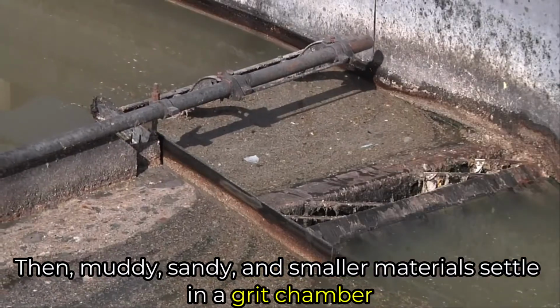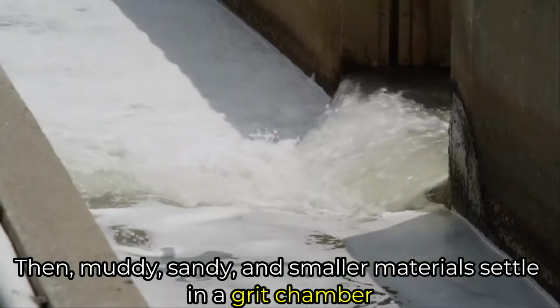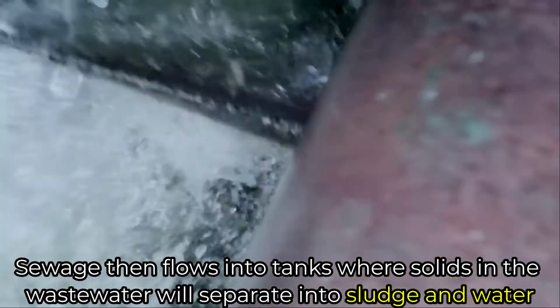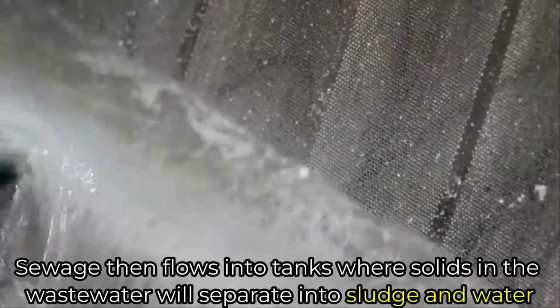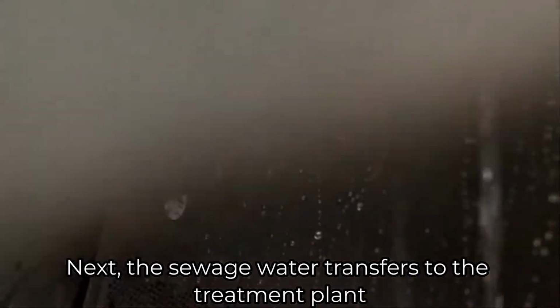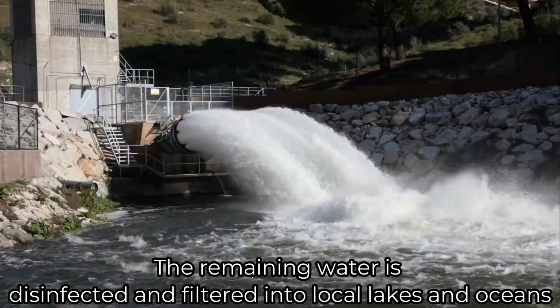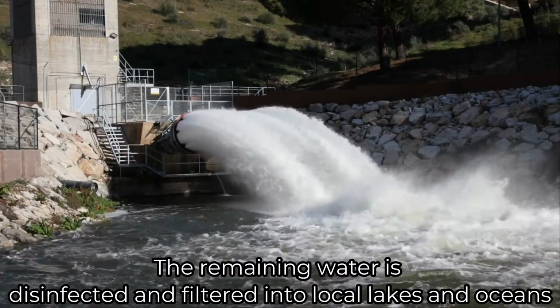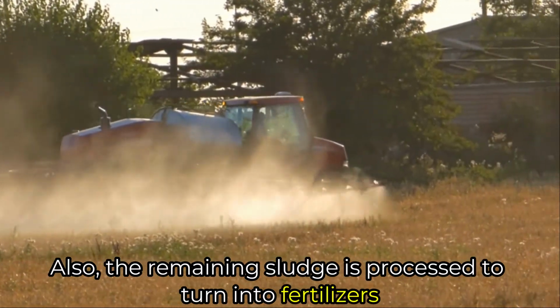Then, muddy, sandy, and smaller materials settle in a grit chamber. Sewage then flows into tanks where solids in the wastewater will separate into sludge and water. Next, the sewage water transfers to the treatment plant. The remaining water is disinfected and filtered into local lakes and oceans. Also, the remaining sludge is processed to turn into fertilizers.